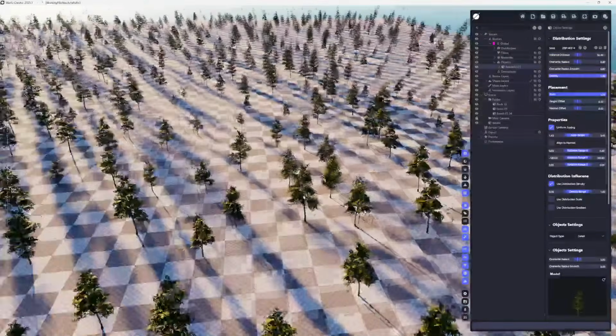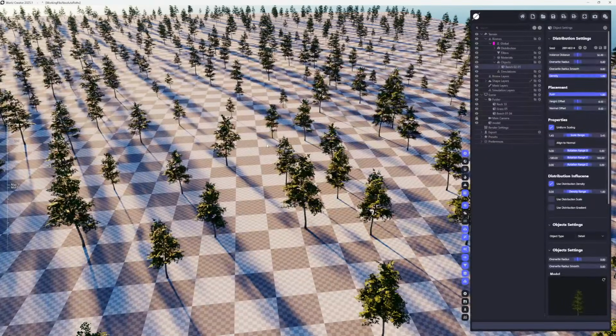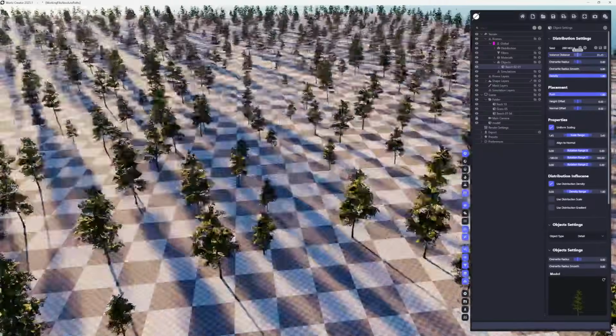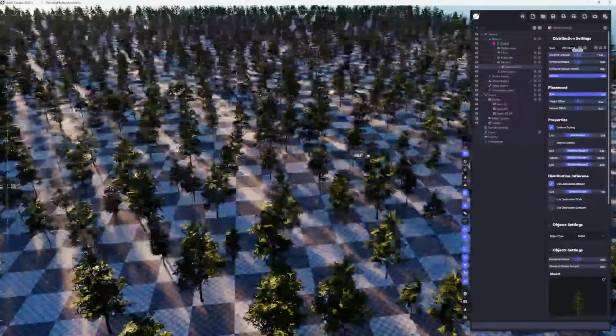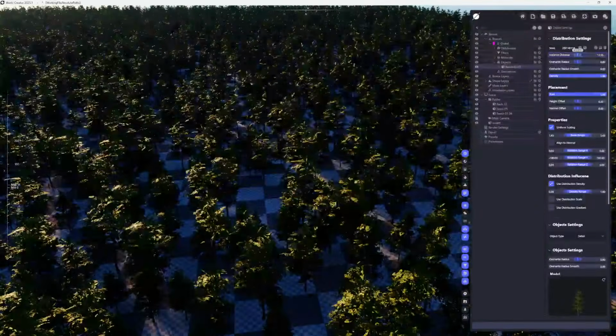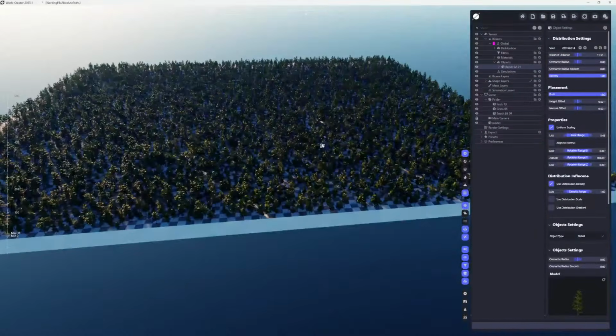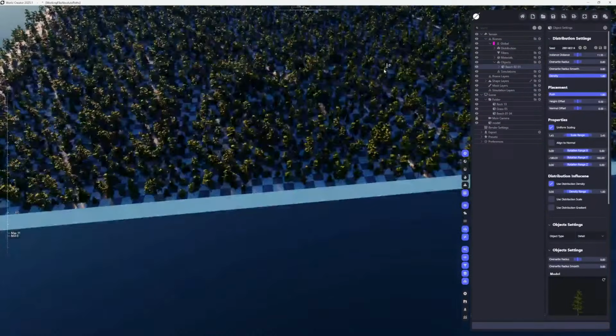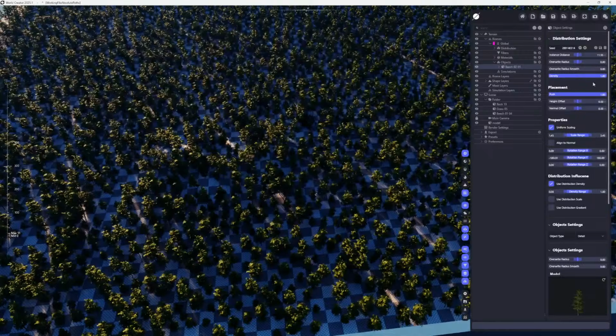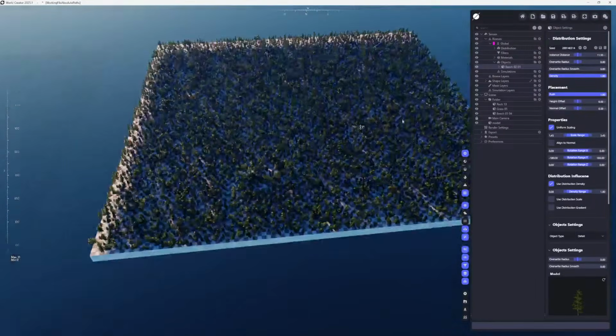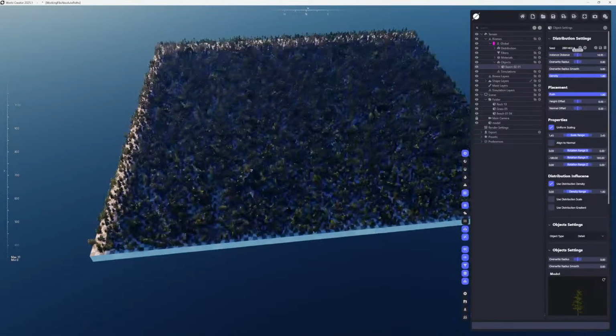This means that the distance between each of these instances is currently set to 32. So if you reduce that, basically the distance gets smaller and the objects are getting way more into the entire scene. So you're now placing a lot of objects already here, and we can really see this mass placement.